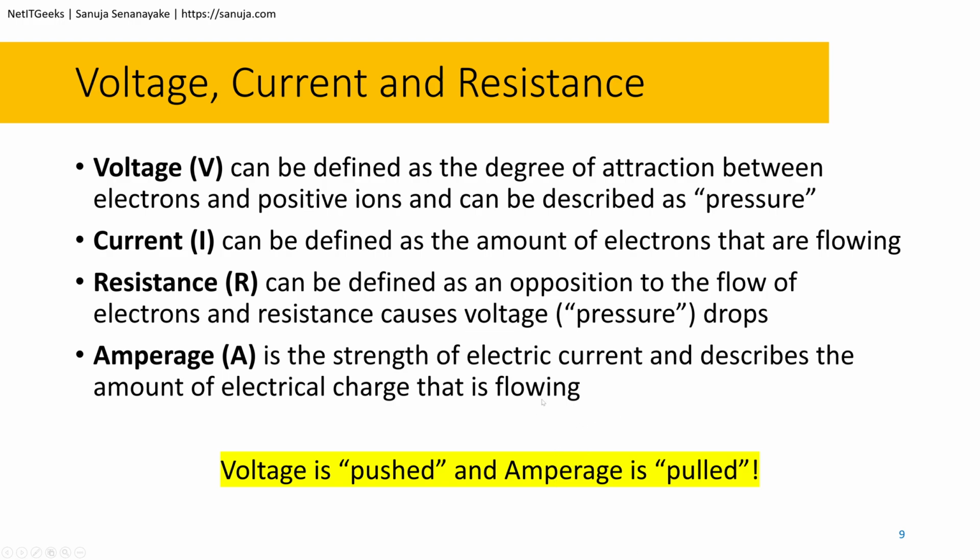If you plug in a device that requires a higher amperage, but your power source cannot provide that type of amperage, two things could happen. In 99% of the time, your device will not power on. So if you have, let's say, a PoE camera plugged into an Ethernet cable, and the PoE injector is not capable of providing that amperage, the camera will not turn on.